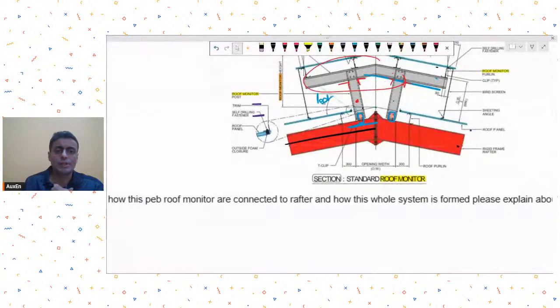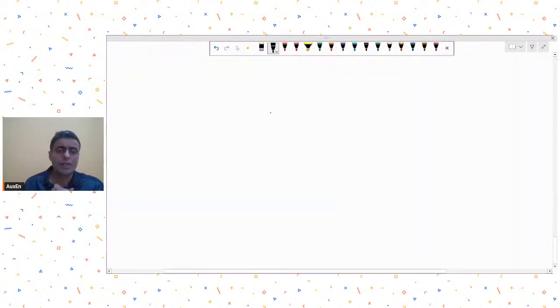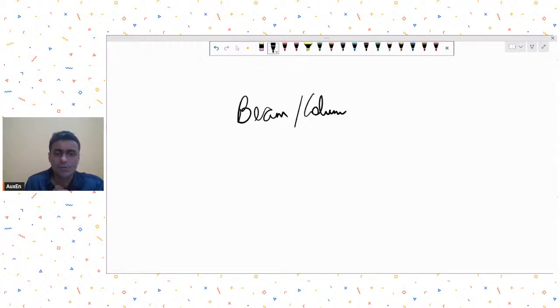So if you are in zone 3, 4, 5, as per the current IS 1893, you have to consider the beam column capacity ratio. It is only allowed to be ignored at the roof levels, and that too if you have a structure which is 4 stories or taller. So you cannot ignore it as per IS 13920.